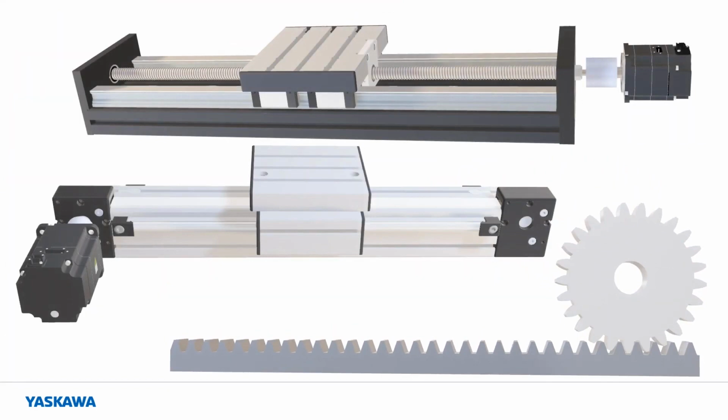Manufacturers have developed ways to reduce the backlash in actuator technologies and electronically compensate for it in the control system. But there is always some level of backlash, and it tends to get worse as the mechanism wears. It means that the position of the load once again cannot be exactly determined by the position of the motor encoder, and it can also lead to tuning instability and noisy operation as the load effectively disconnects from the motor for a short time upon reversal.